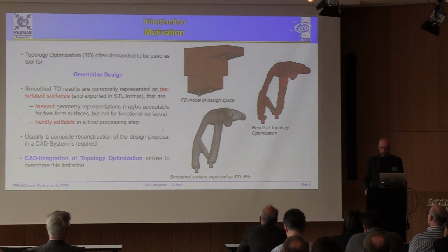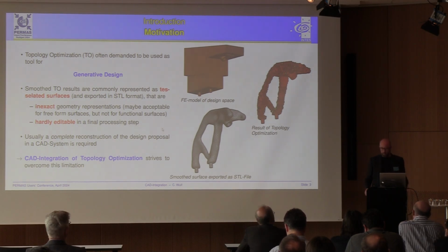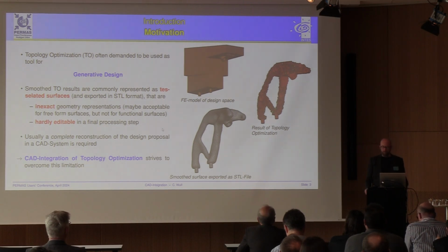You see an example on the right side where we have an FE model of a design space doing topology optimization with clear results and also considering manufacturing restrictions, and finally get a result that is at least close to a manufacturable design.